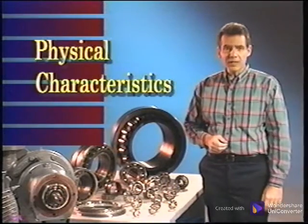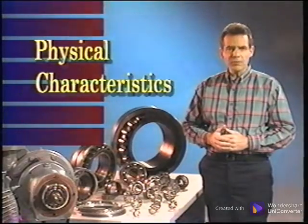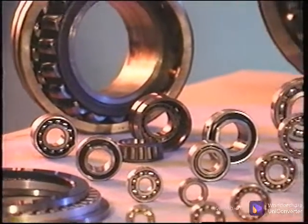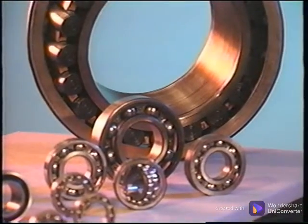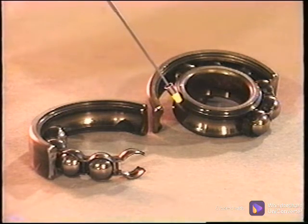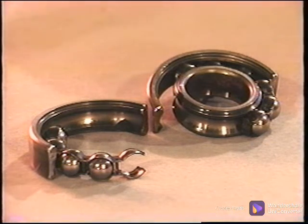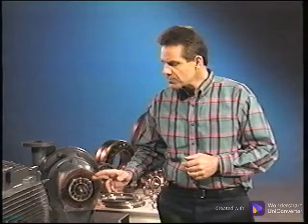Let's look at some of the physical characteristics of bearings to understand why we see the spectral and waveform patterns that we do. Each of these bearings has individual characteristics due to its own unique physical geometry, which cause specific frequencies to appear in spectral data when a defect is present. These defect frequencies can be calculated individually for the outer race, the inner race, the cage or fundamental train, and the balls or rollers. Let's take a look at how these can be approximated using an actual bearing on a shaft. The defect frequencies are often expressed as a multiple of the turning speed of the shaft.